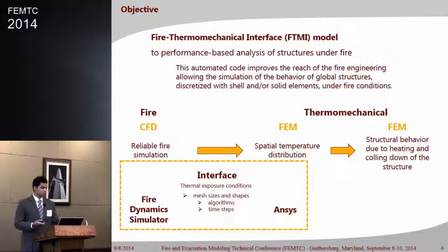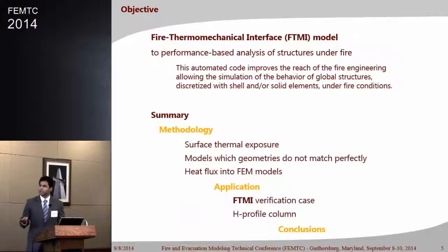Right now, this interface is running between Fire Dynamics Simulator and ANSYS, but the methodology can be applied to any other codes. In this presentation, I will start with the methodology, where I explain how we calculate the surface thermal exposure, then how to handle models with geometries that do not match perfectly, and how to input the heat flux into the finite element method models. I have two applications here. The first one is intended to verify this interface, and the second one is an application to an H profile column. At the end of the presentation, I have some conclusions.